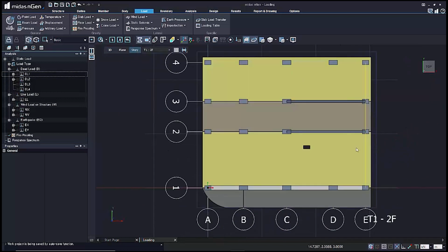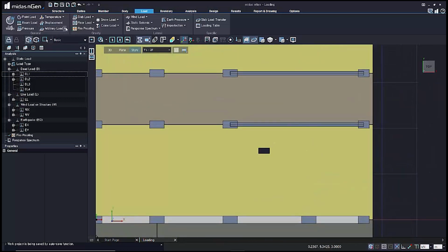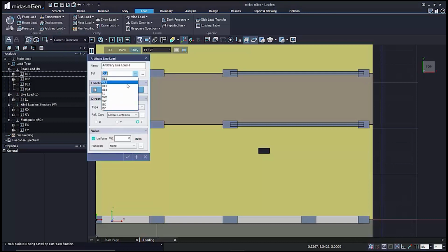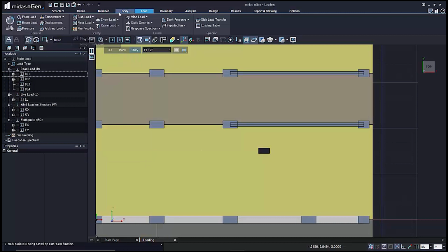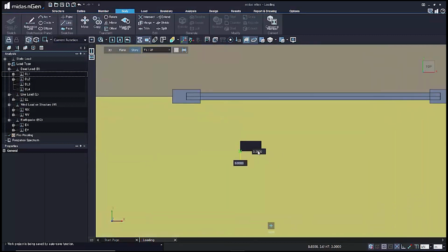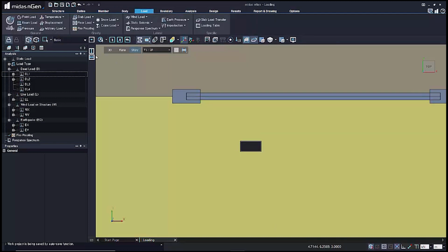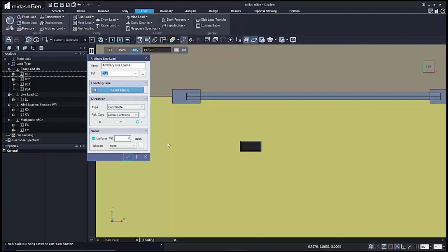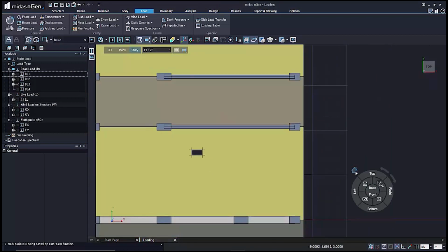The following process is the dead load 3, the opening load. Assume that equipment is placed on the opening boundary line. We are going to input the line load. At this time, use the body line. Body is totally different from member. Member is for design, and body is just a tool and an object for assigning members and loads.